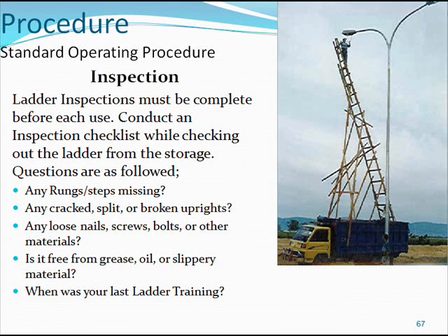Inspection. Ladder inspections must be completed before each use. Conduct an inspection checklist while checking out the ladder from storage. Questions are as follows. Any rungs or steps missing? Any cracked, split, or broken uprights? Any loose nails, screws, bolts, or other materials? Is it free from grease, oil, or slippery material? When was the last ladder training?